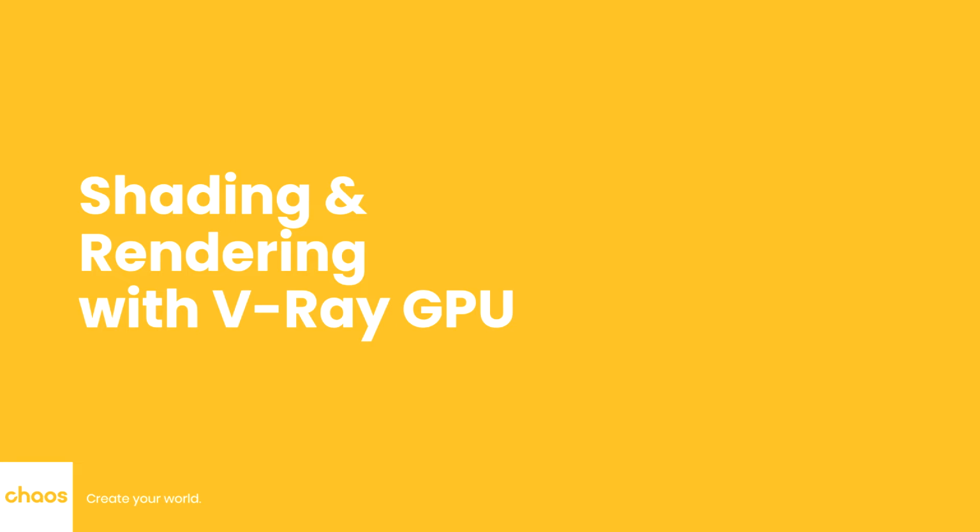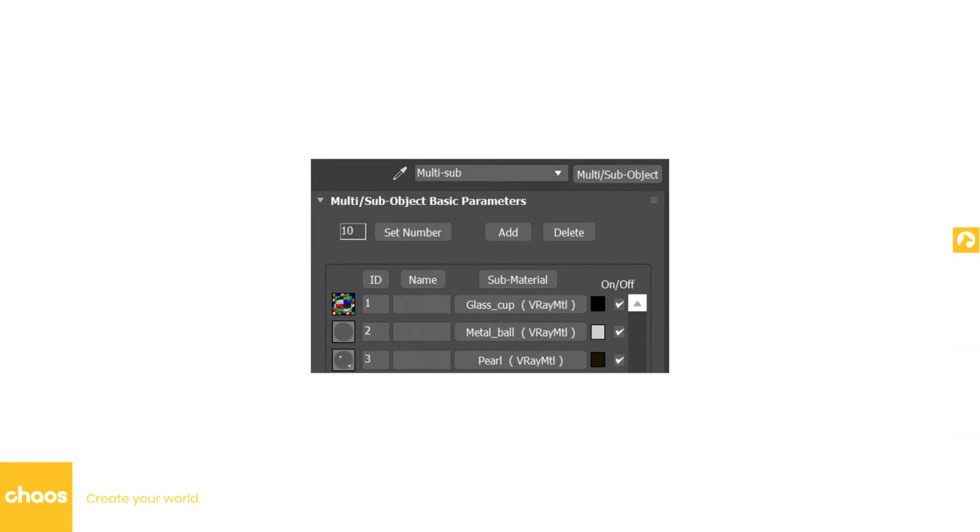Finally, we have reached the last stage of the process, shading and rendering with V-Ray GPU. The lighting for this scene is quite simple. We use a V-Ray dome light with an HDRI map. And remember, we added a material ID operator to each event in the tyFlow particles, with the glass cup set to ID 1, the metal ball to ID 2, and the pearl bubbles to ID 3.